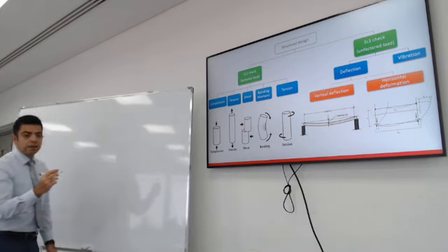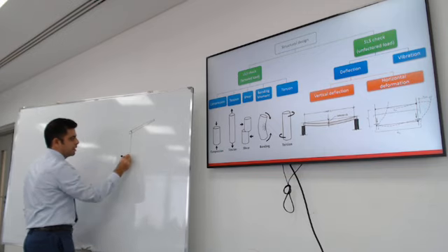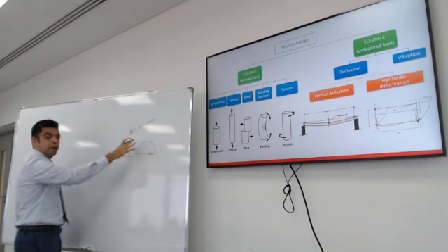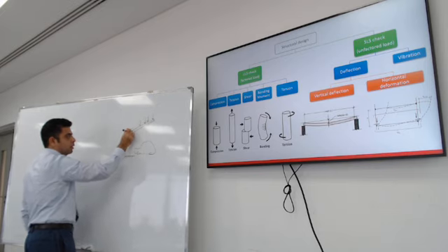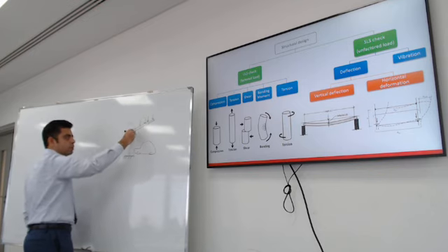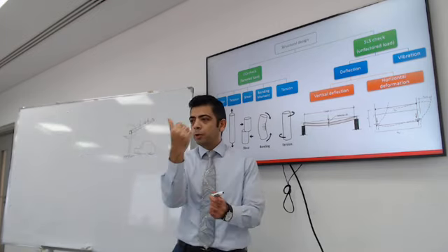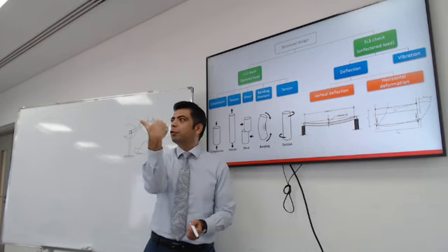If you have a parking structure that has a canopy that looks like this, and this is a column fixed at the bottom, and the cars would park here. The weight of this structure, if this was a box beam or an I-beam, will cause torsion. This moment is causing torsion on this beam. So for torsion, you put your finger along the longitudinal axis of the beam. Your fingers are showing you the direction of torsion.